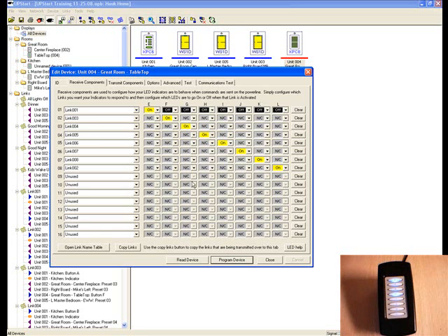Setting up the LED tracking is very important. Knowing how you want the buttons to interact is more important. Do you want all of the buttons to be on at one time, or possibly be on at one time? If each button controls an individual light, absolutely. I have an 8-button keypad, and each button controls a different light in a room. What if I have it set up as multiple scenes? Yes, I can continue adding on to scenes, or I can tell each scene that when I activate you, I want you to turn everybody off.